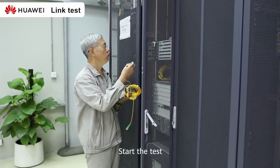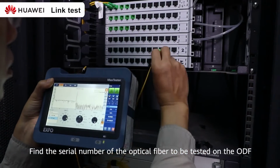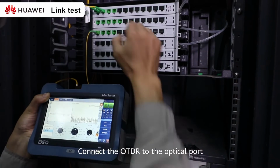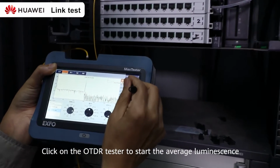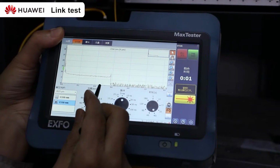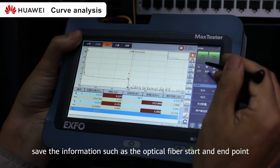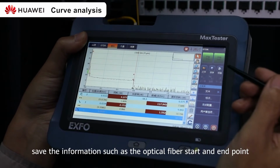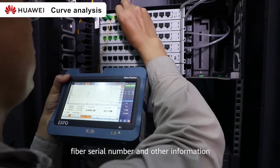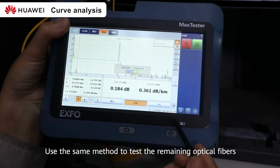Start the test. Find the serial number of the optical fiber to be tested on the ODF. Connect the OTDR to the optical port. Click on the OTDR tester to start the average measurement. After the test is completed, save the information such as the optical fiber start and end point, fiber serial number, and other information. Use the same method to test the remaining optical fibers.